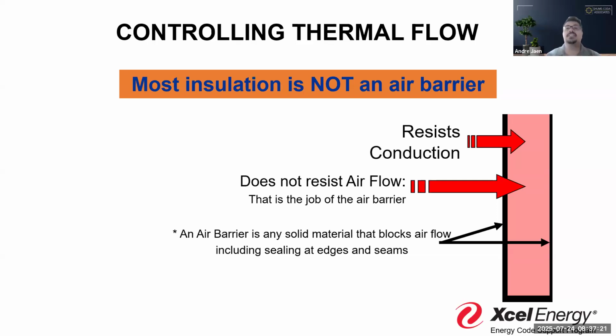Then we only get the one side of this when we talk about maybe the weather resistive barrier, maybe we have some exterior insulation, some continuous insulation on the exterior, and sealing those joints will help produce a more sealed building. If we're doing a remodel, right, we're gutting the kitchen on the inside of the house and it abuts an interior wall, something like that.